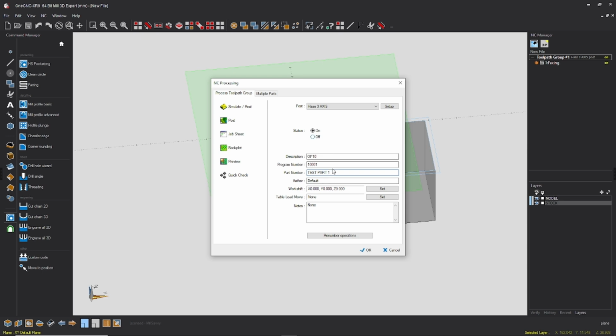Alright, put your name in here. See, I utilise this information here. I'd for instance put the title of the job, your drawing number, issue level, who done it, what date, and then I'd also put the datum, say G54, so using G54, where my X comes from.